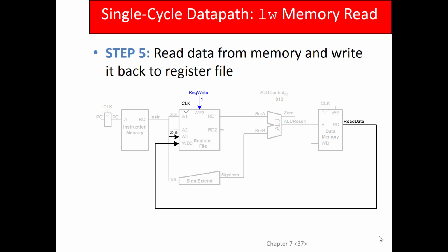I don't waste anything. And then you have to tell the register file there's a write enable, if you remember from that Verilog I showed you. You only want to write when you intend to write. You only want to write if you're executing an instruction that writes to the register file, which is just about every instruction except for branches and jumps.